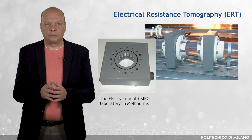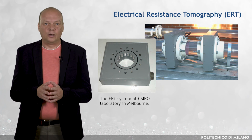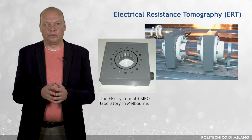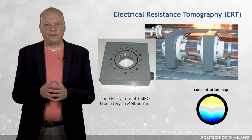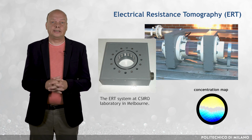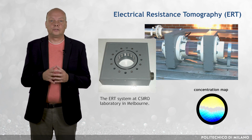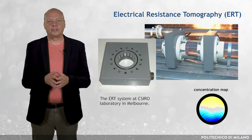Electrical resistance tomography, ERT, is by far the most common form of tomography used in laboratories, being relatively inexpensive, safe, and rapid. The technique involves sensing of local conductivity and its relation to the local solids concentration to get a concentration map of a pipe cross-section.